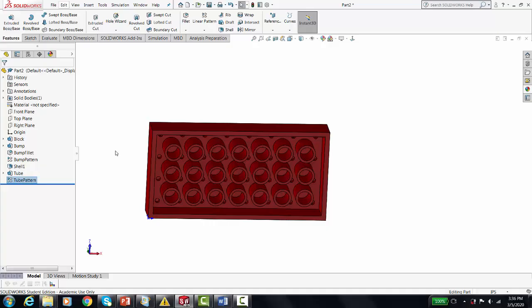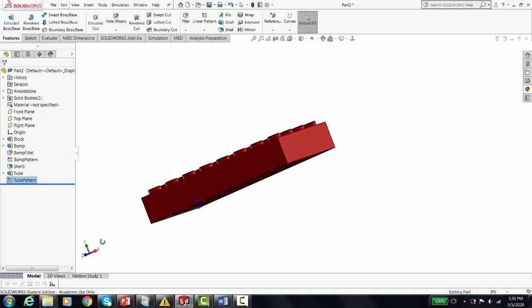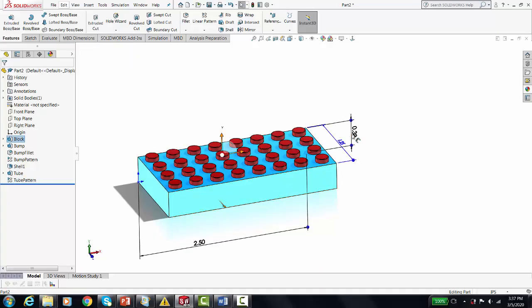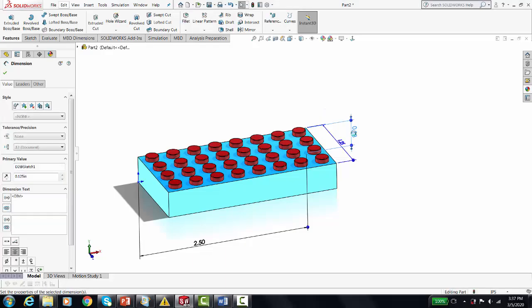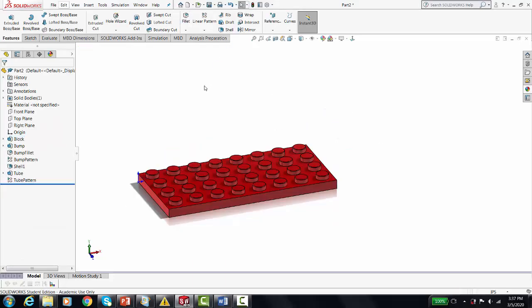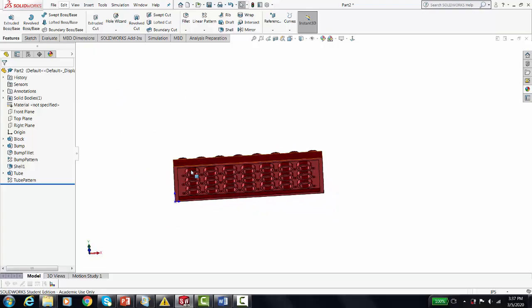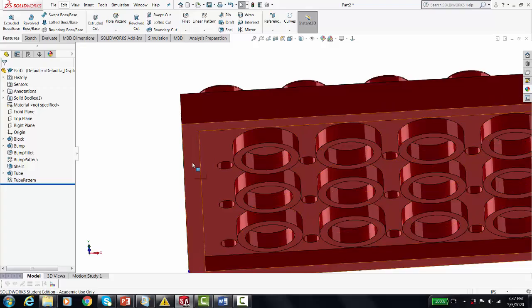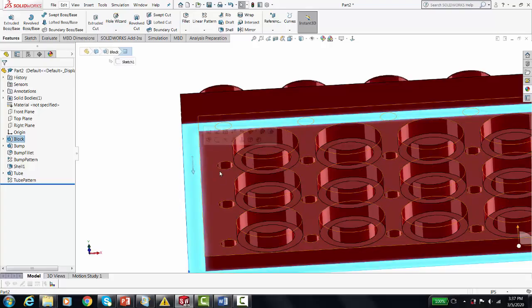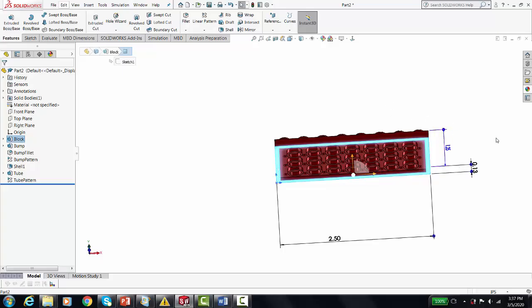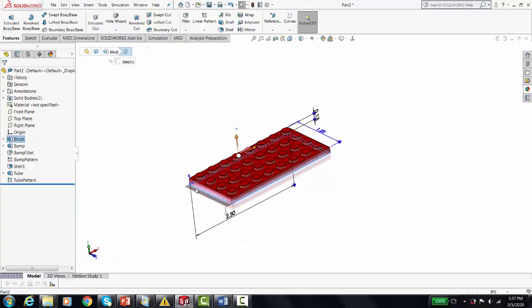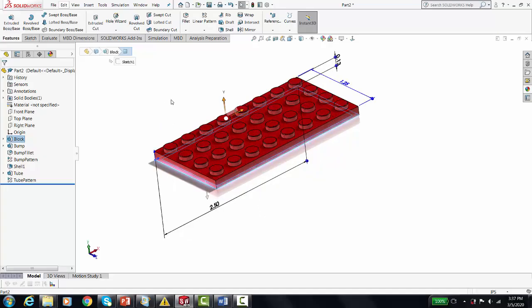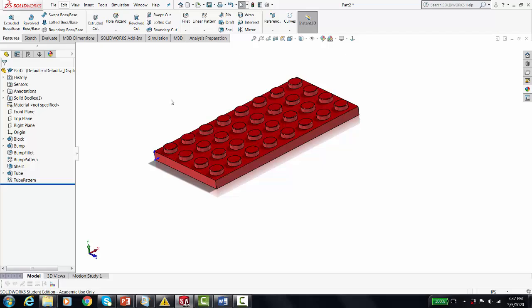I can quickly update and change the size of my Lego block. Oh, one last thing. Let's see if we can change the height of this block. Here's 0.38. A short Lego block would be 1/8 of an inch tall. And if I make this change, hopefully everything sticks together. The tubes go up to the surface, so the tubes automatically shrink because they just extrude up to the surface. So we're looking good. So this is the Lego block. And in the next video we'll look at changes to make this Lego block into a different shape and kind of test our design intent to see if it allows us to work with this Lego block and manipulate it and make a potential series of Lego blocks.